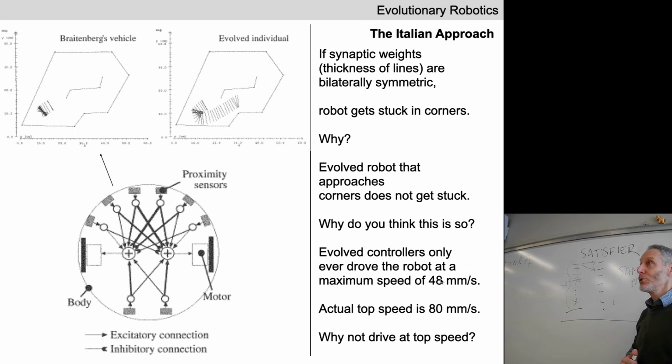This is as good as evolution could get the robot to do under the constraints that the robot has to operate under. Yep. If you were to add more sensors that are firing at different times, would that allow you to go much faster? Fantastic, absolutely, right? I don't know whether these 8 sensors were refreshing or pulsing in sync. If they were, that was probably not a good design decision. We could add more and put those pulsed infrared sensors out of sync. They'd be sending out signals at different times. And assuming this relatively simple neural network can deal with that wrinkle in the design, maybe this number would climb higher if we re-evolved it. Absolutely.